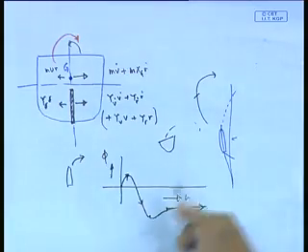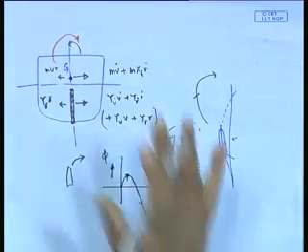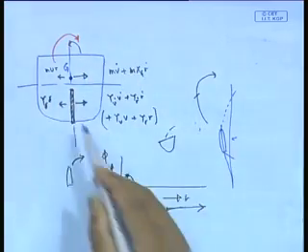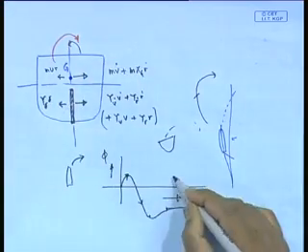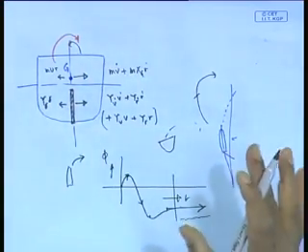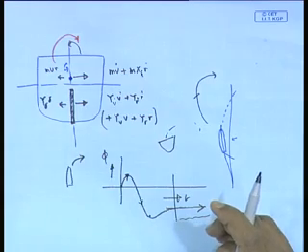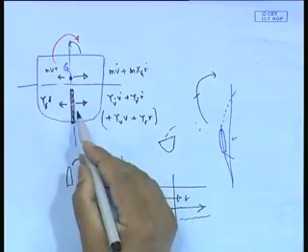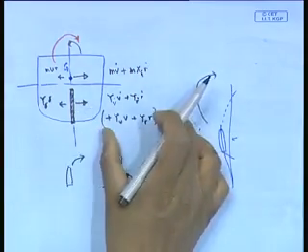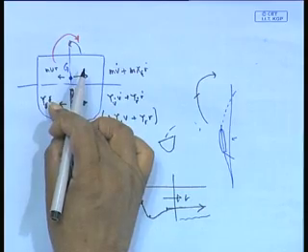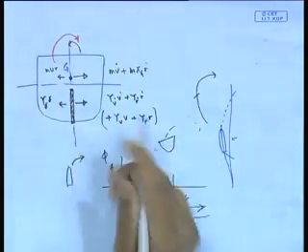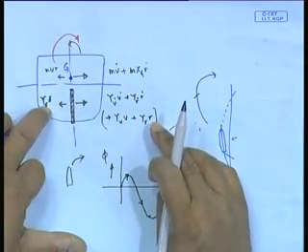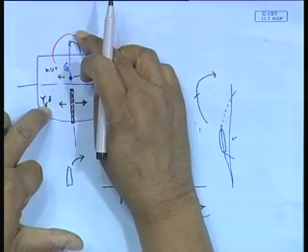Okay. The interesting point here is that I will also explain, but from the physical picture you can understand. Suppose you are turning outward. Now, suddenly the captain decides to bring the rudder to 0 quickly. What would happen? Remember, the net force acting here is this minus that, which gives me the moment, which gives me heeling.